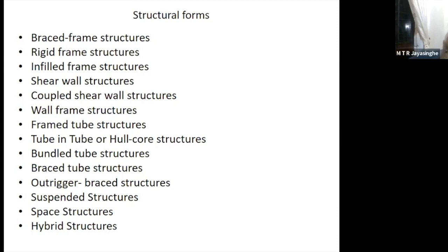It's like a table. So the moment you socket more, if there's peaty soil, you will socket at least 2.5 to 3 meters into the bedrock. The reason is you want almost perfect anchoring of the pile into the bedrock so that you have a fixed end condition at the bottom, and you can make a fixed end condition at the top.